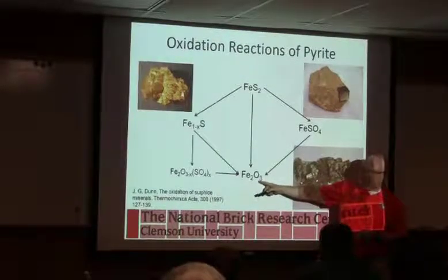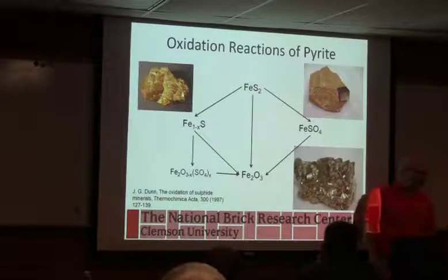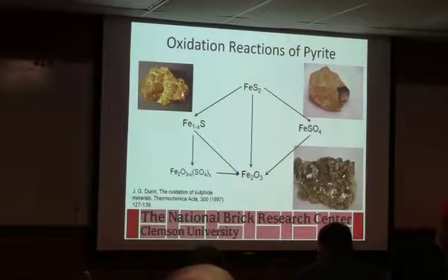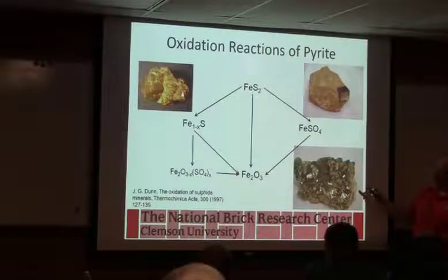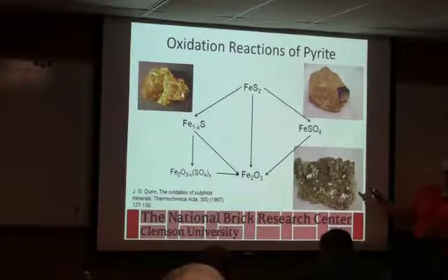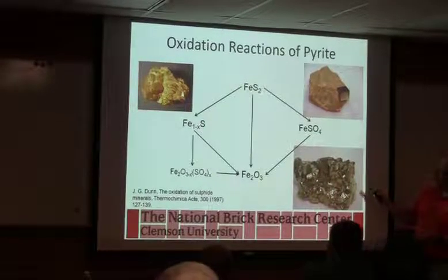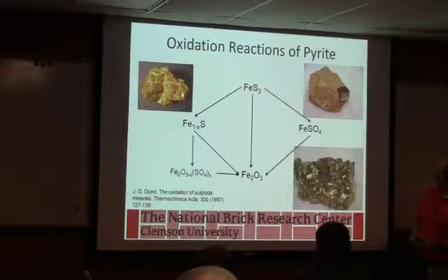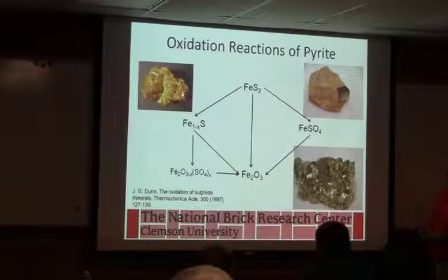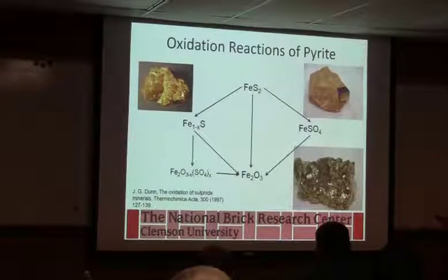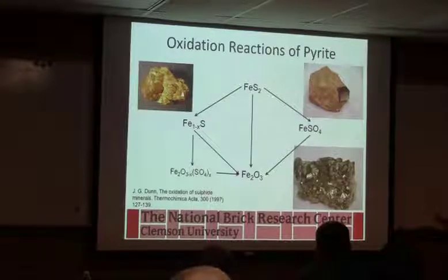on its own. There are places out west where they're mining, it's pretty well known around copper mines and tin mines. There's a lot of pyrite in that, and those tailing piles, when they get wet, they make sulfuric acid. So they have to have special controls. That sulfur, with water, becomes sulfuric acid and can damage streams and plant life and all that kind of stuff. So it's something to look out for. We don't have enough pyrite to generate any level in a pile to worry about.